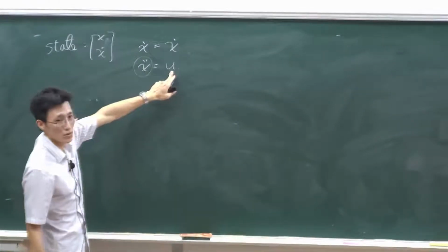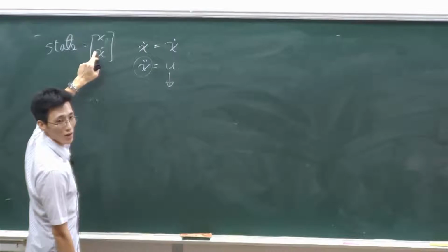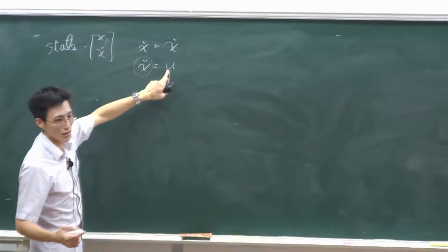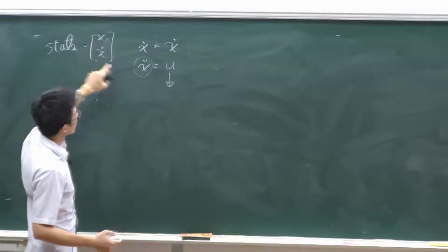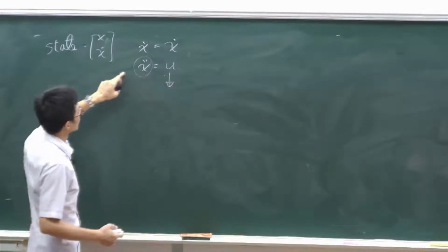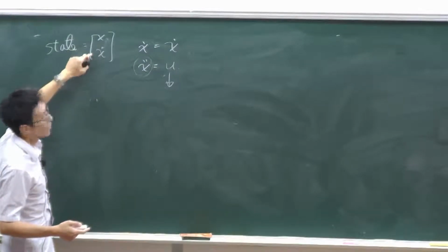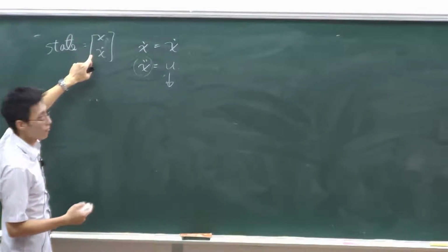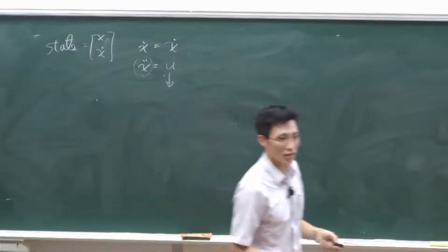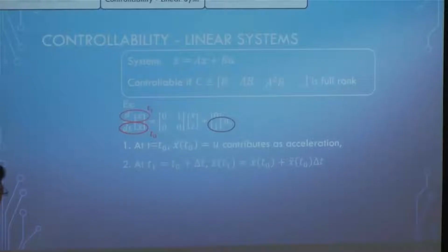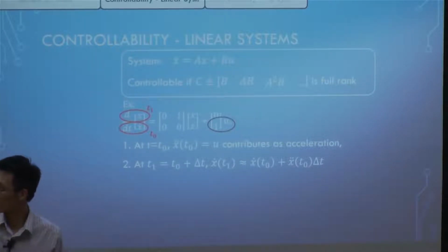We want to see if your control input can affect both states in time. Controllability means, given a control, whether you can control both states. Because it's an equation, we can see that it can control the acceleration. But what we wonder is if we can control all the states, which are position and velocity. For sure it can control acceleration. But as time goes, it's hard to say, right? So let's see the next time at t equal to 1. What happens using that equation?